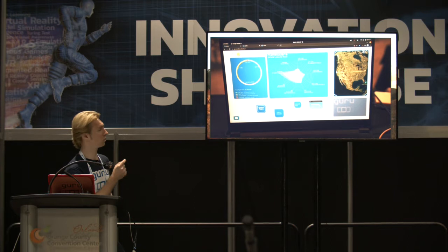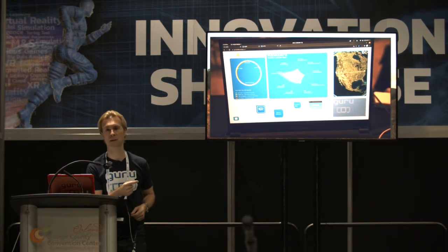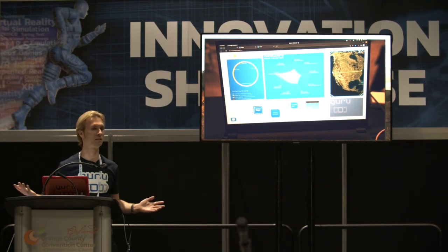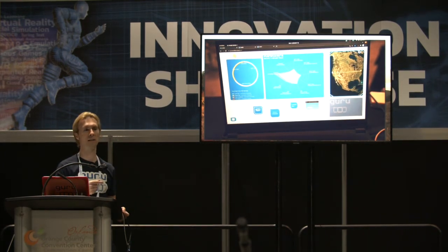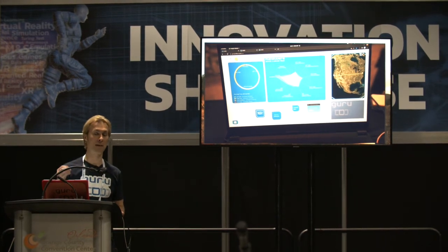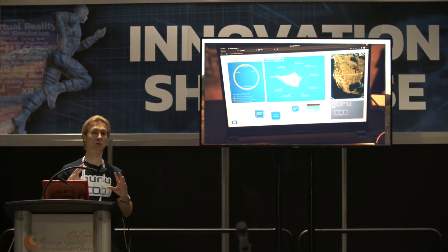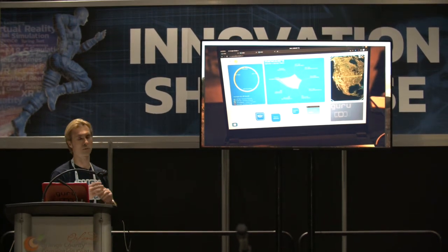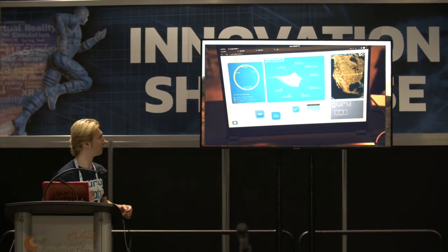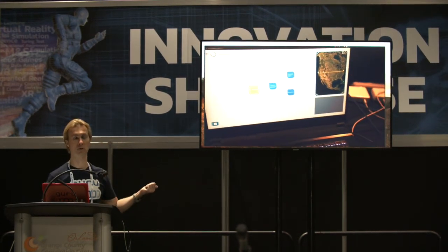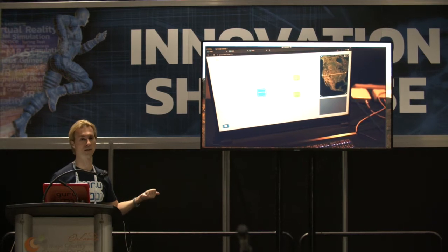And now Dustin has just hit the auto-populate button because today, it's kind of boring to run just one simulation. Let's run 60 simultaneously. What auto-populate does is it creates a Latin hypercube space-filling distribution of trajectories around the baseline settings he's just chosen. So we're going to run a threat space of trajectories today. And Dustin's hitting submit. Now Guru is setting up those trajectories, batching them off, and running them as well.